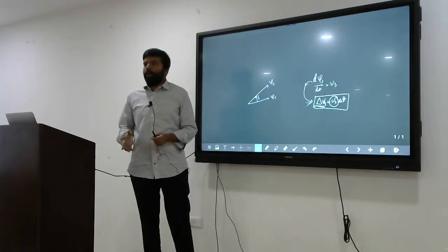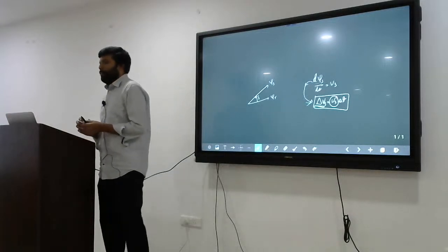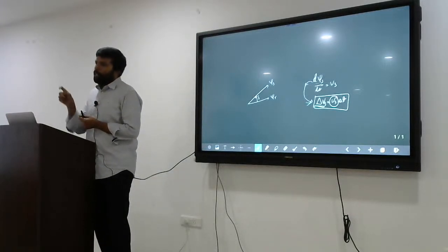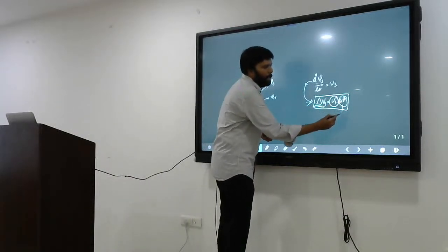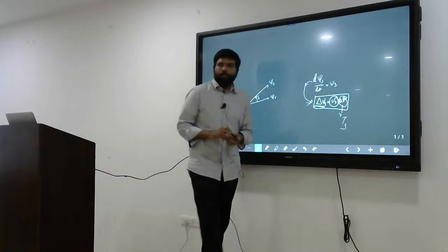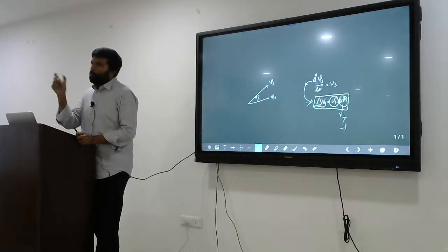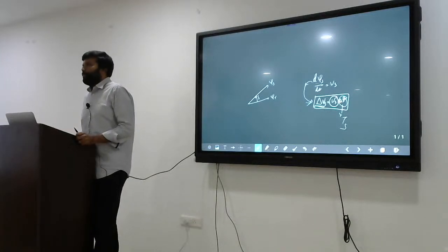So the final conclusion is, from this expression, we can conclude that the flux vector we can control effectively in a particular control period. This is nothing but the control time. This is nothing but Ts, the sample period, control period. Within this period, by choosing the proper voltage vector, we can control the stator flux effectively.